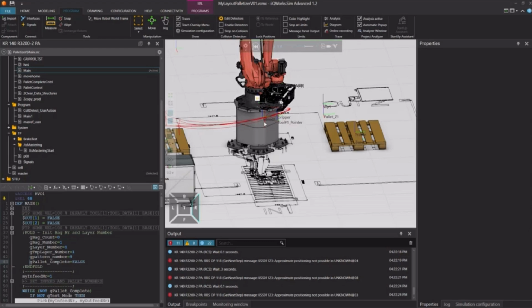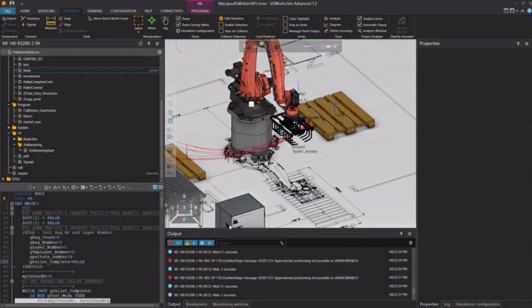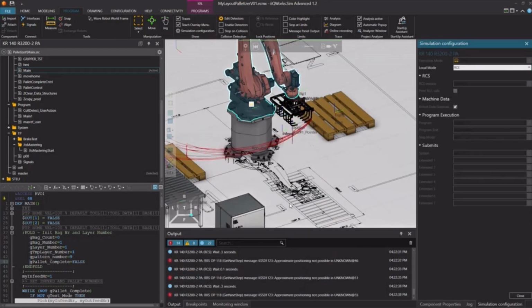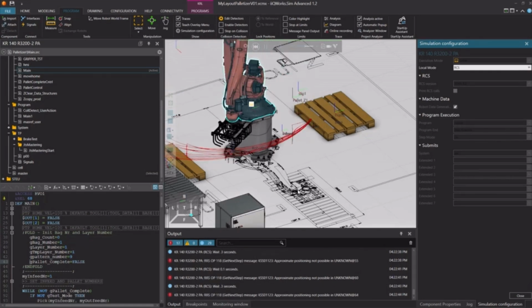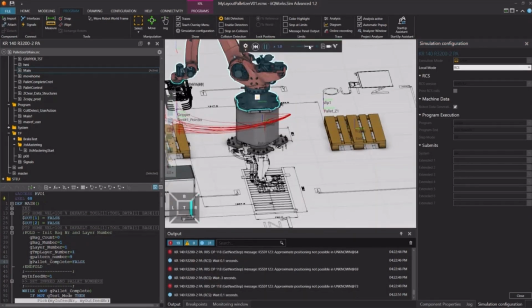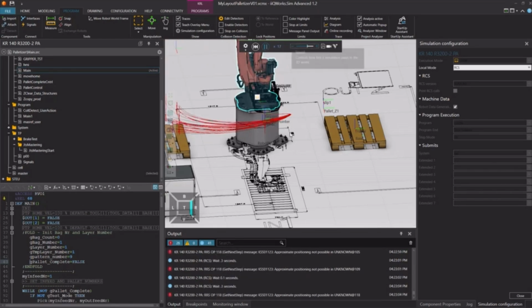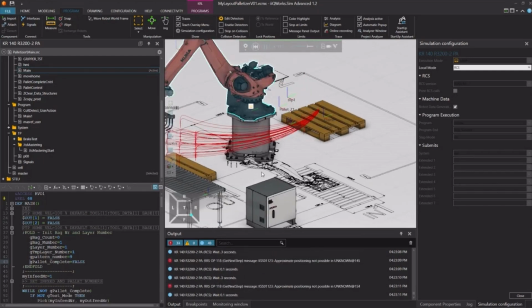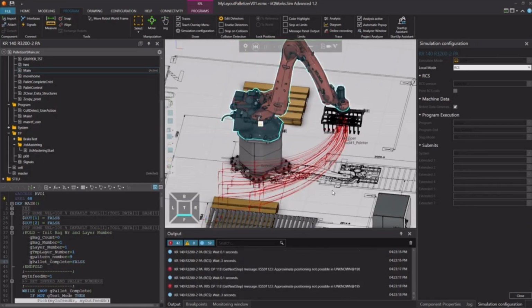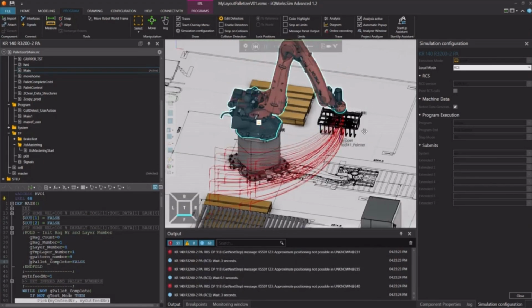Trace visualization clearly shows the robot motion path during execution. Debugging tools and robot controller simulation allow monitoring of global variables in real time. The palletizing sequence completes one side and transitions to the opposite pallet as expected.